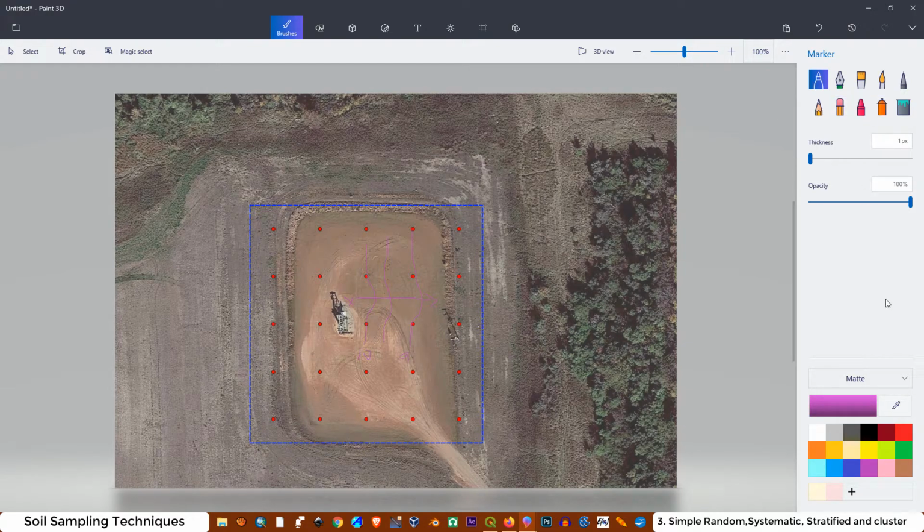Then the contaminated area is going to be all this area at the depression. But as we take the sample systematically, we are missing all this area, right? Then with the systematic sampling technique, if there is a pattern in the contamination, it could be a problem, and we are not going to identify the contamination.